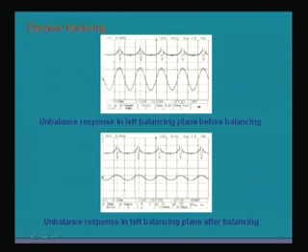What we did was balance this machine, and then again we measured the vibration of the shaft. You can see that quite a decrease in the amplitude of the vibration took place when we dynamically balanced the rotor. These are the actual measured signals from the rotor kit which I showed earlier. So there is a drastic decrease in the amplitude. That means the force which was coming from the imbalance got reduced drastically.